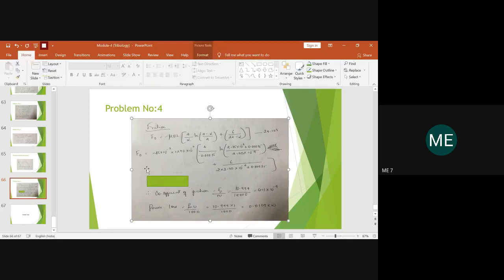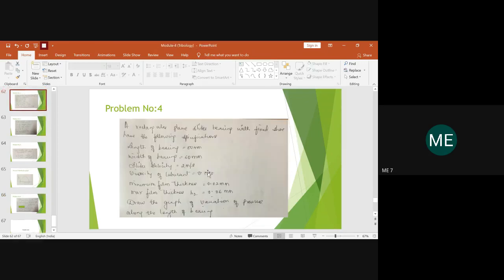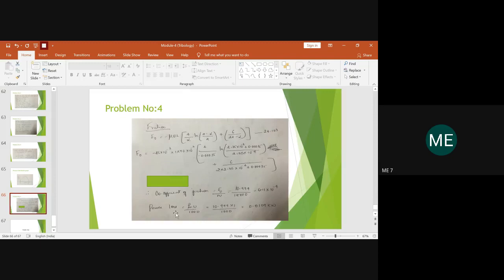So in the equation, you need to check what the value of the coefficient of friction is, right? So if we go back, sorry, in this they haven't asked, it is just pressure distribution. Fine, then leave it. If along with this they ask you to determine the coefficient of friction value, you have to go and calculate it, which is nothing but F naught upon W.